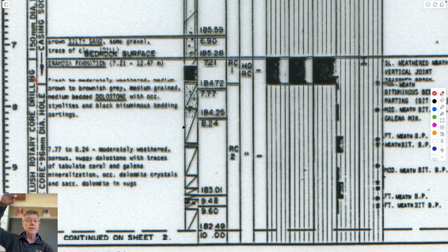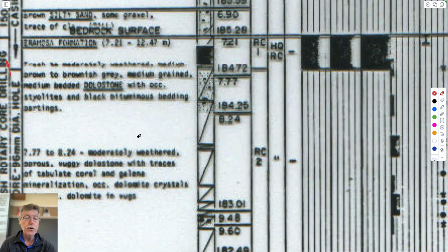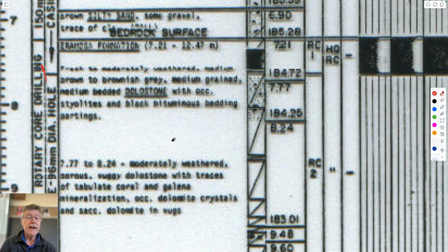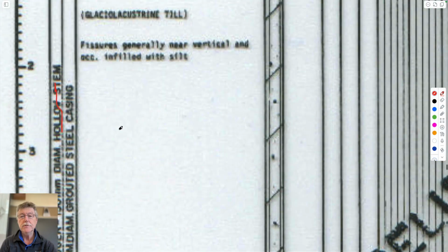The core might be 100% of the length of the borehole, so every part of it would be covered. Not all of it might be retrieved, some of it might be destroyed or fall apart. And then some description by you of what the characteristics of that rock are. Limestone, sandstone, fractures, no fractures, staining as a sign of water flowing in it, etc. All kinds of things you could imagine.